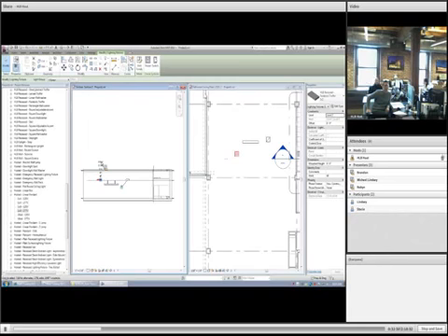Revit's a very stable program, except sometimes in those locking instances, you'll have files go bad because they're saying, oh, there's too many dependencies being built up. So just use it sparingly. That's what I would say. In fact, locking to the ceilings, I think that's perfectly fine.